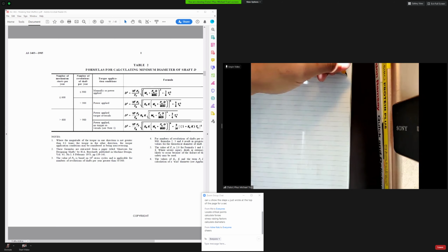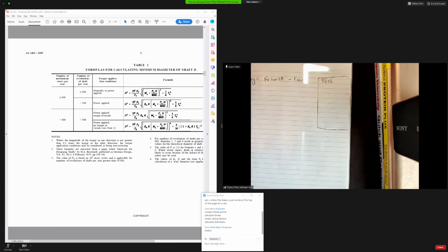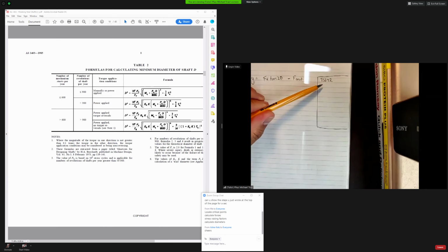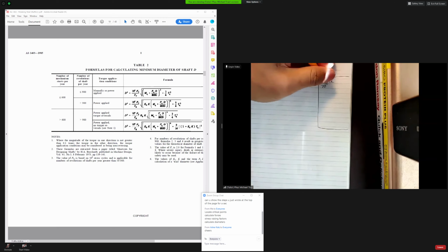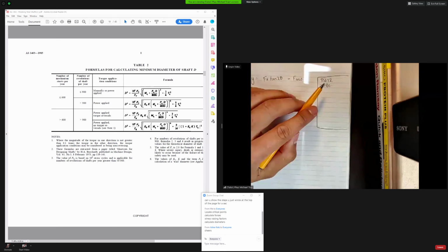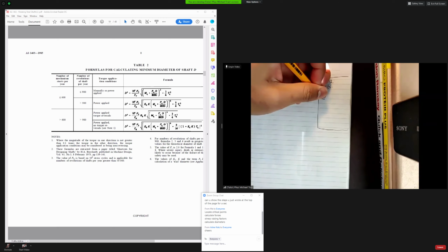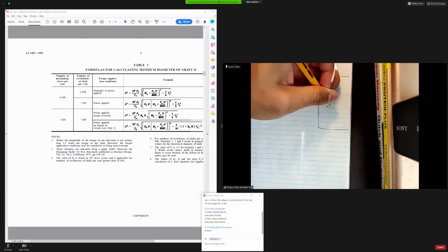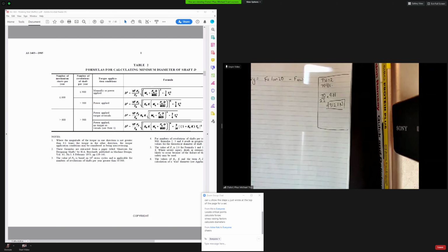And for FGW, for the TS672, from the gear catalog, there's information on the TS672 that tells you that it's 70 pounds. So from pounds to newtons, you would go 70 divided by 2.2 times 9.81, and that'll give you 312.1 newtons. Remember, that's from the gear catalog. Whichever gear that you choose, go there and find the weight of it.